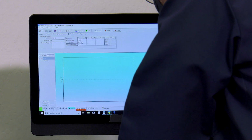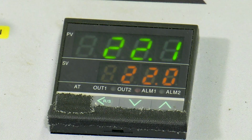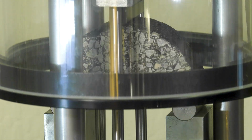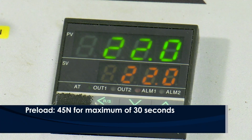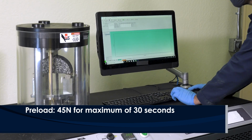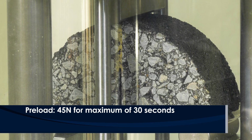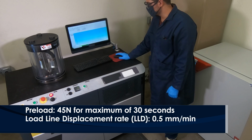To conduct the test, enter the information in the test controller. Set the test temperature of the environmental conditioning chamber to the specified test temperature. Allow the chamber to equilibrate. Once the test temperature is reached, apply a 45 Newton preload to the specimen for a maximum duration of 30 seconds to ensure the sample is seated properly. Verify proper level and position, then release the load. Now the test is ready to start.